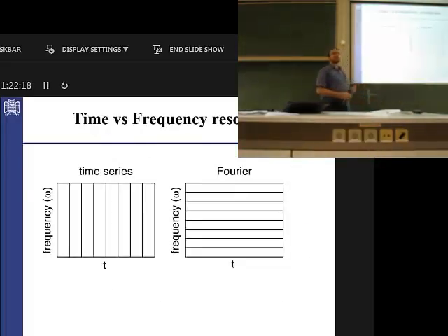In the time domain, in time series, you have samples of the signal. You have no notion of the frequency. It means that the frequency resolution is blurred. You have no details in the frequency, but you have resolution over the time. In the Fourier analysis, the STFT, DFT, whatever, you lose the information over the time.